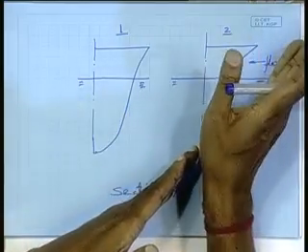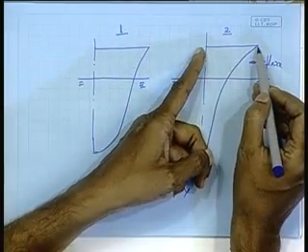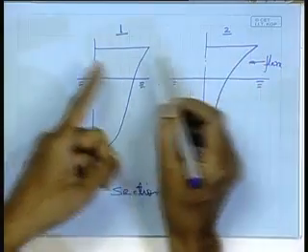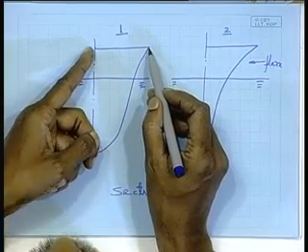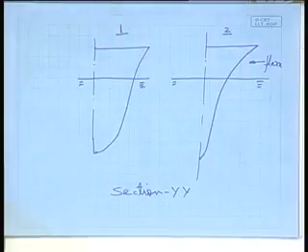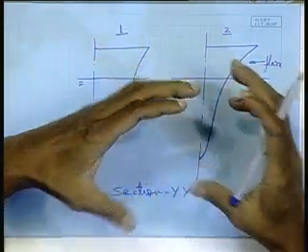So, you provide a much bigger flare, so that you achieve the required deck area, right. Less flare, much flare is not needed, because you do not unnecessarily widen the deck, okay. So, these are actually based on the requirement of block coefficient and other aspects.